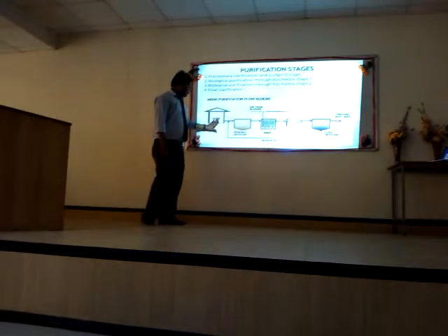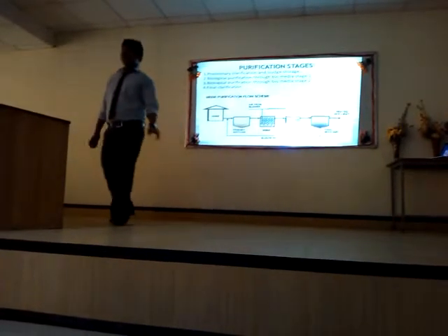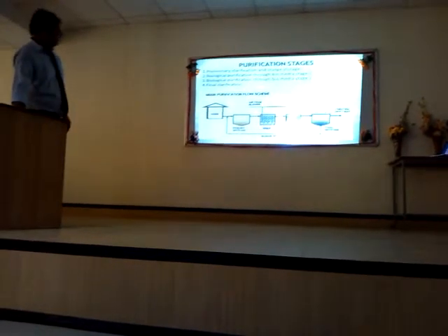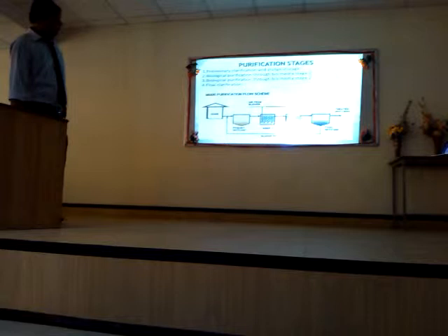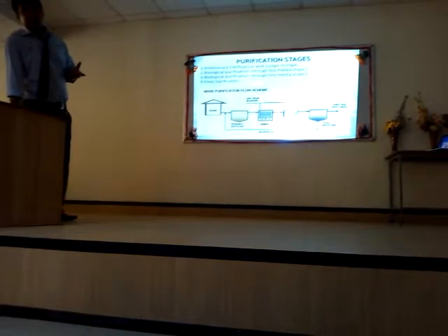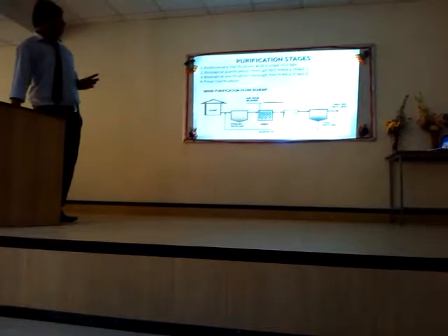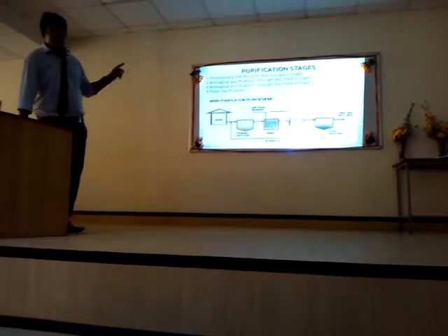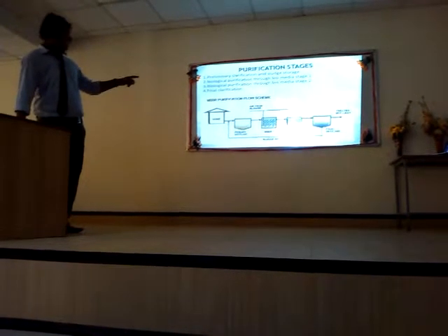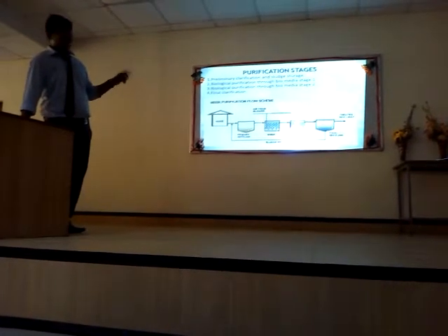The raw water comes from here, then it goes to the primary settling. Whatever sludge is there is settled here. After that, the water goes into the MBBR. In the MBBR there is a process of aerobic and anaerobic bacteria. The first and second are the same, but if there are some impurities, they are cleared in the second MBBR. After that comes the final settling.